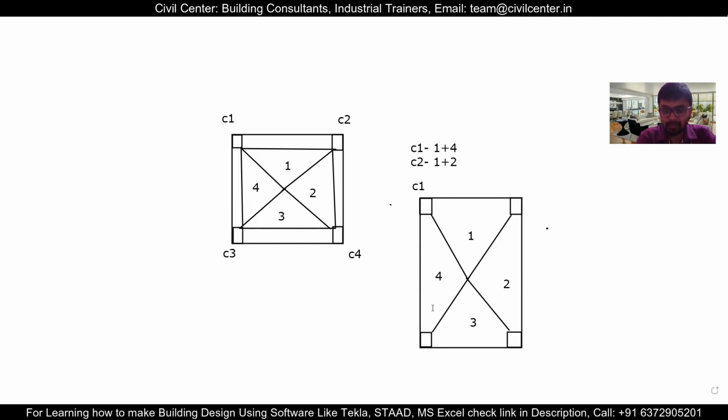So the load along this particular vertical is more than the load taken by the horizontal. So that's why we're going to use the orientation. When we give the column orientation, we'll use the orientation in which its length is along the vertical. So if you're going to provide an orientation here, we're going to provide 250 cross 300, where this one will be the 250 and this one will be the 300. That is, 250 will be the horizontal dimension and 300 will be the vertical dimension. So why 250 to 300? Because basically when we start any project, if we want to give a square size, then we generally provide 250 columns.